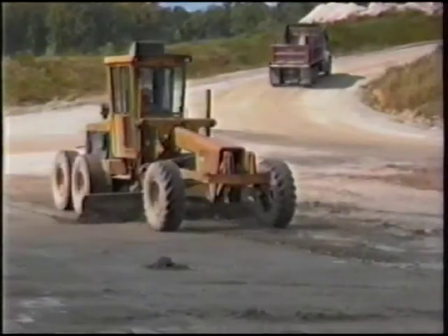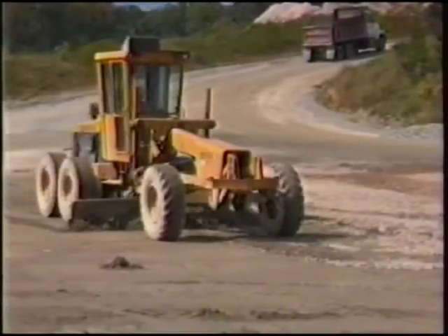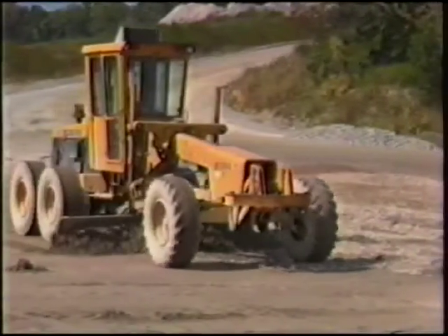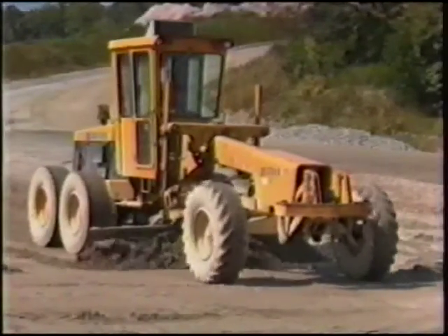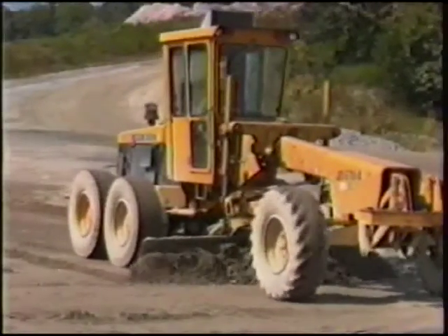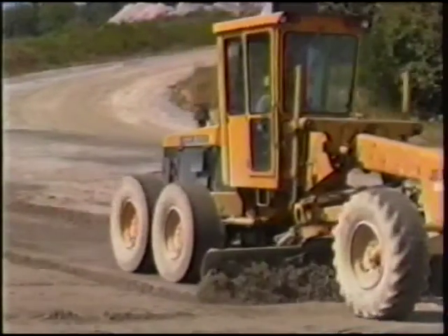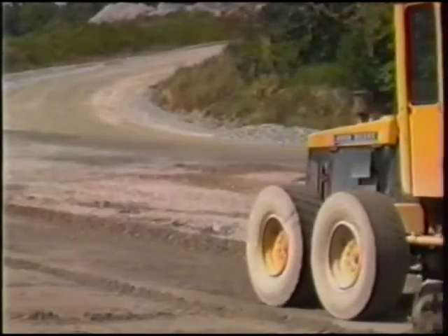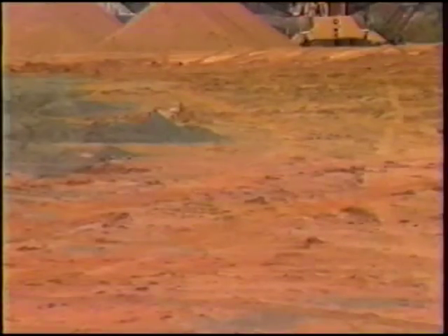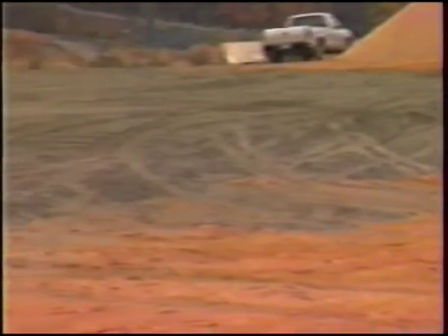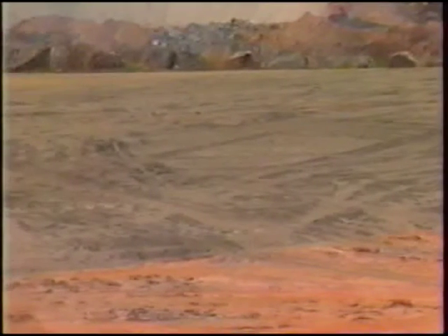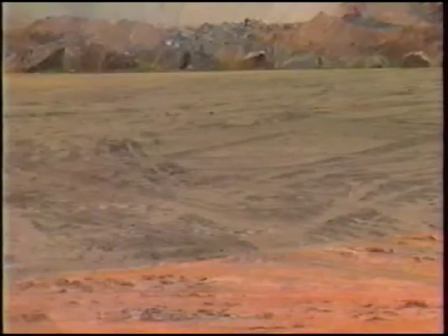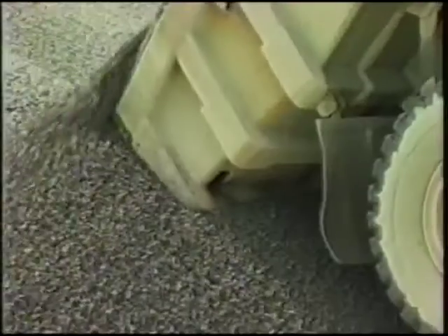The first thing that must be done in constructing a proper stockpile is to select a good location. The area should be thoroughly cleaned with no foreign material left behind to contaminate the aggregate. The area should be graded relatively smooth so that water will drain. If possible, a distinctly different and smaller size aggregate should be used for a layer at the base of the stockpile. This area has been cleared and graded for a new stockpile. Crusher run is being placed on the ground to separate the pile from the ground. This will keep the water out and prevent any contamination from the ground.